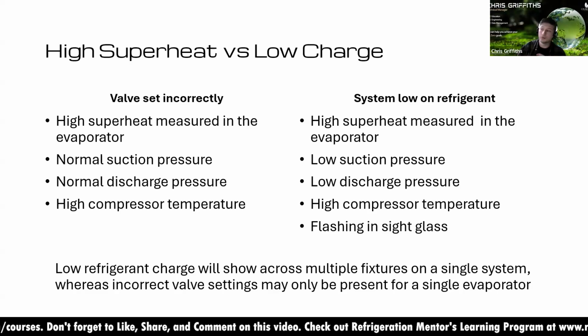Also, low refrigerant charge will occur across the system, whereas incorrect valve commissioning, or a valve not opening enough, should appear just on one or two fixtures. If it's across the entire system and your site's been commissioned incorrectly, well, that is an item there, but you'll probably have to dig a bit deeper into it to check.